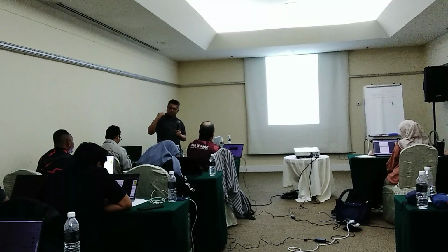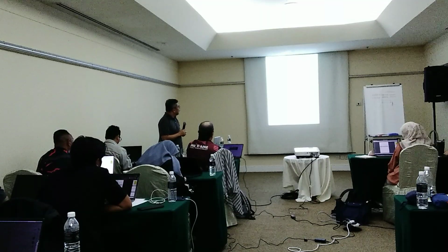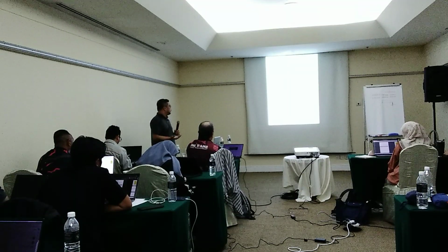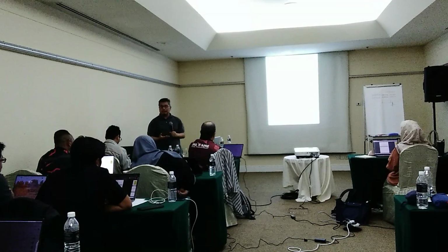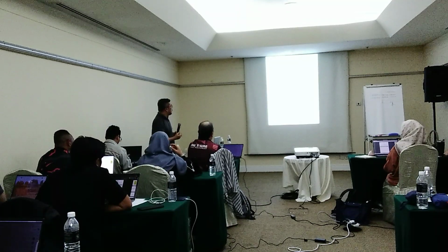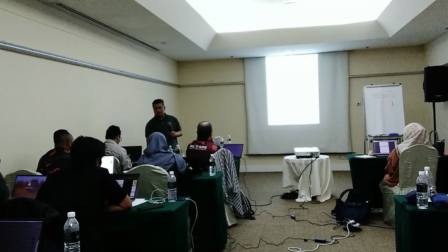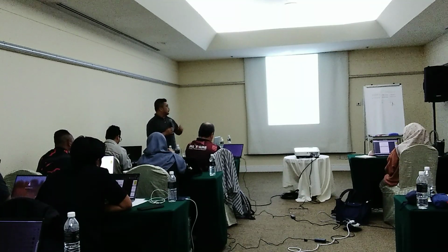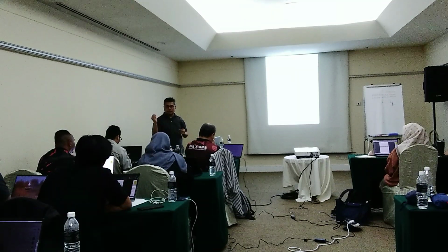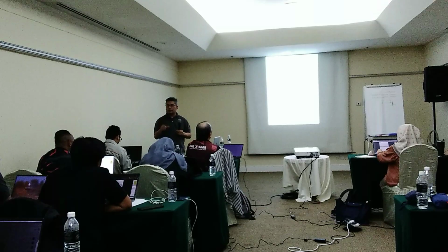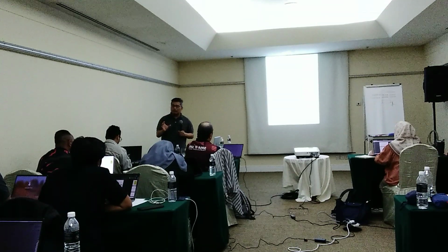You have to list them all and continue with the format. And then RPN is severity times occurrence times detection. That is the risk priority number. Without the detection, severity multiplied by occurrence is the risk, regardless of whether you can detect or cannot detect. Severity multiplied by occurrence is the size of the risk that you are facing.